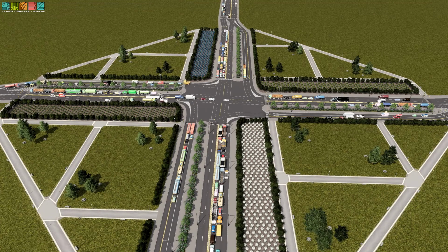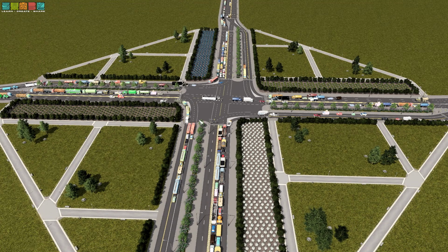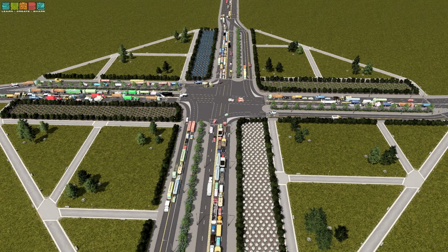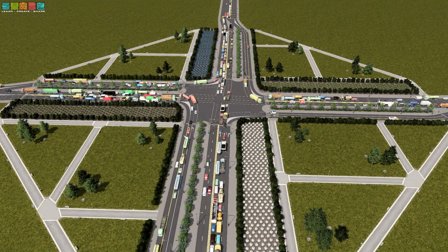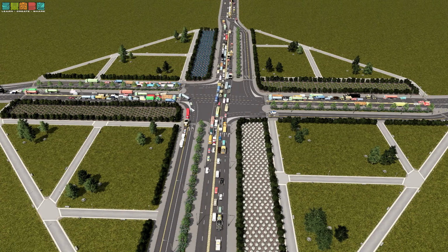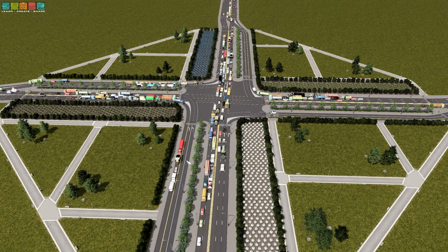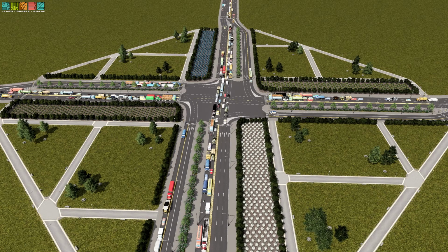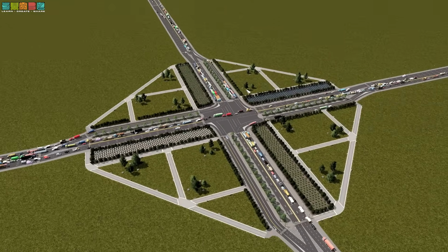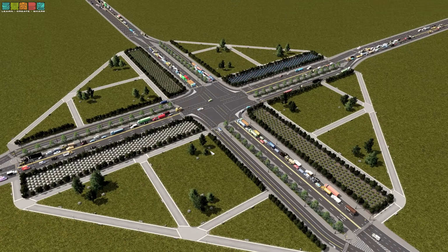The left turn traffic and the straight through traffic all has to stop at the same time. The right turns are entirely free-flowing, so any car that shows up in the right lane is allowed to go. And here we see the displaced left turn doing its work. So that traffic is allowed to turn left over this traffic because it's already out of the way. And that is essentially it. It's a very simple 2-phase light in the middle, in theory.